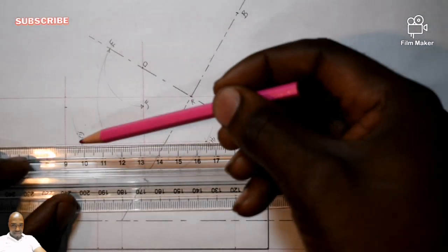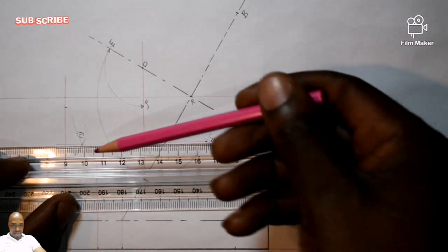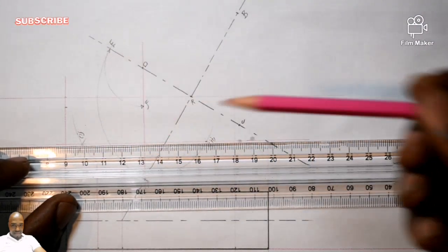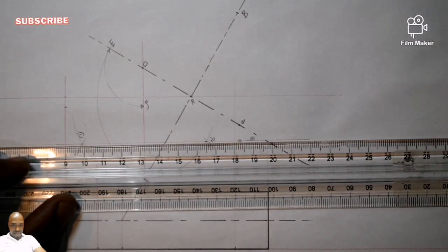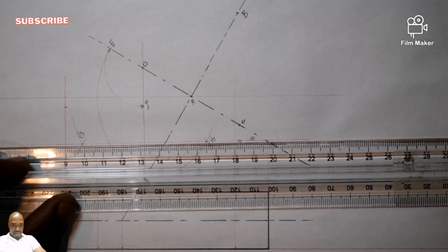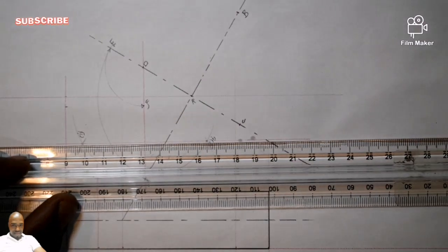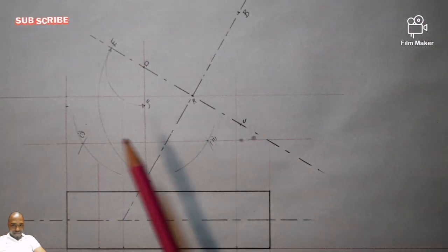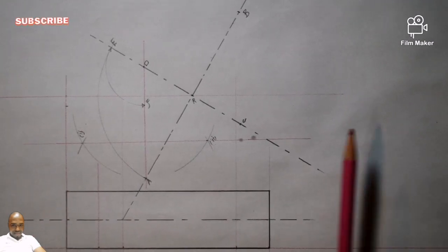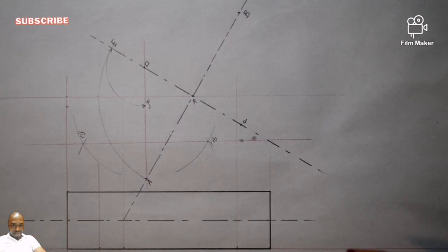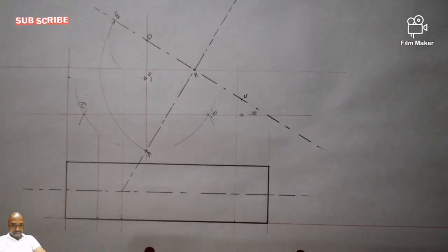So somebody might say, I'm joining Roman figure 1 and 2, so you just start here and end here. No, center lines and constructional lines must always exceed your drawings, your points, you understand, in your drawing. Constructional lines must always exceed. If I'm saying exceed, do you see, this one, remember, it's out of dimension. You understand? I normally don't like to use the word just.